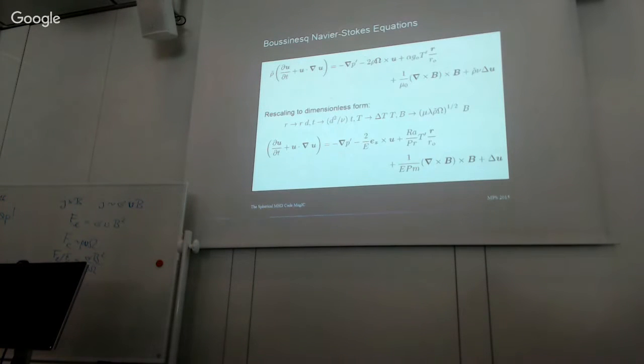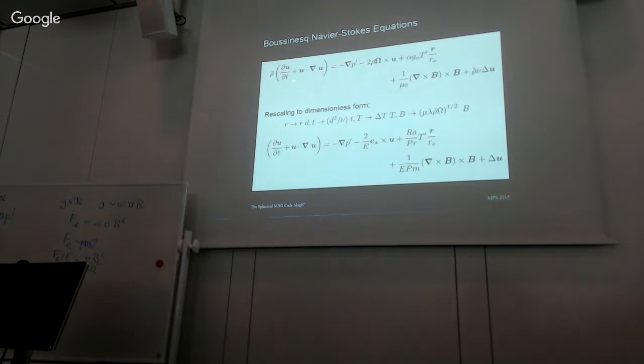Now, you do that, and then you can write your Navier-Stokes equation in this form, which doesn't look too different. But now what we have here is just the first order disturbance around the background state. In the background state there was no velocity, so it was hydrostatic, right? So this is the first order disturbance here. And this rho, which I multiply this with, is the background state. So this is zeroth order, this product is first order. This, you may say, is second order, so maybe small, unless velocities become large.